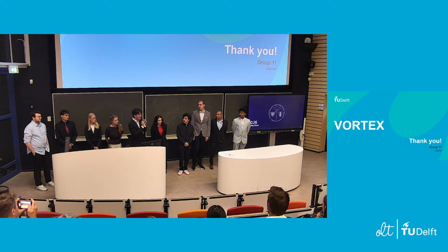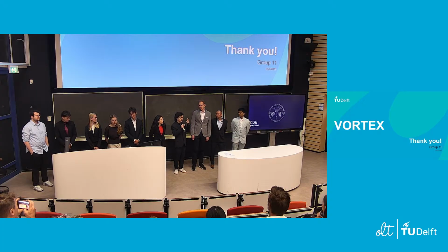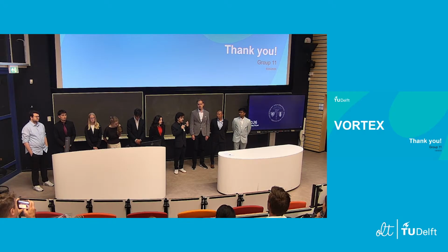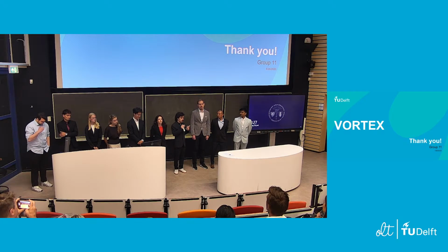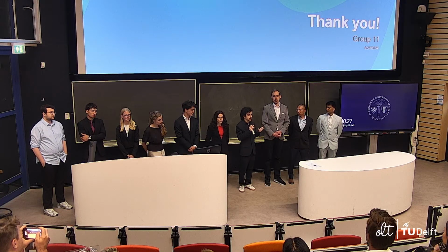Thank you. Could we give a little more clarification on the trade-offs? Okay, Marcos. Our design process was split into two stages. Firstly, the midterm, in which we did all of the preliminary design, so all of the choices that I presented at the beginning. Our main system-level choice was the coaxial or flat pusher-puller design, and our trade-off was mainly based on the confined space, trying to fit within the nacelle, which we considered not an extremely big space, and on weight. We determined weight as one of our bigger driving factors, not because it is extremely important, as the drone should just be able to carry the payload, but because weight is our way of understanding the feasibility of this design.